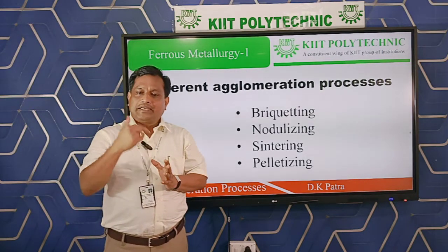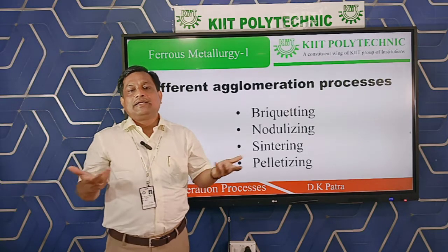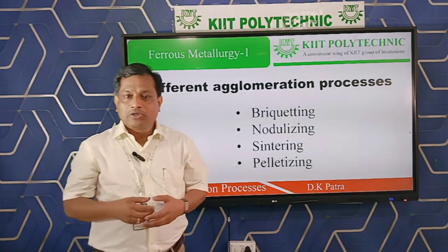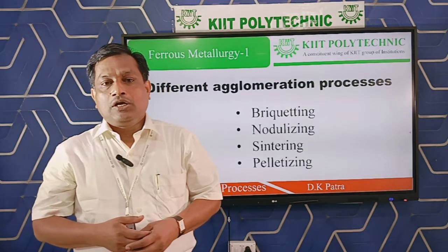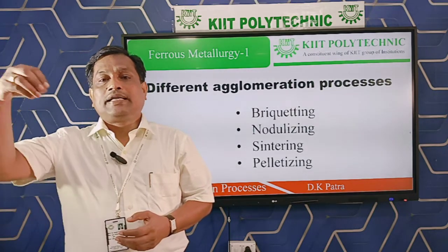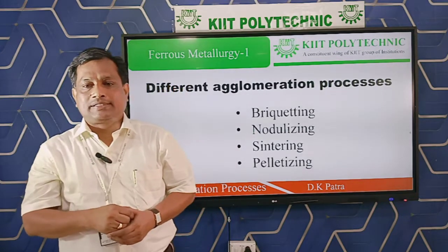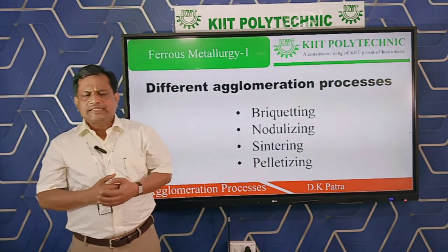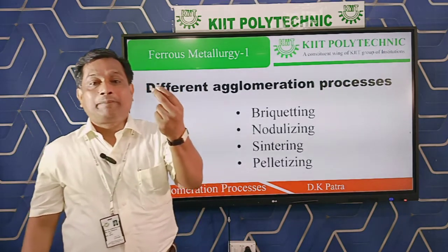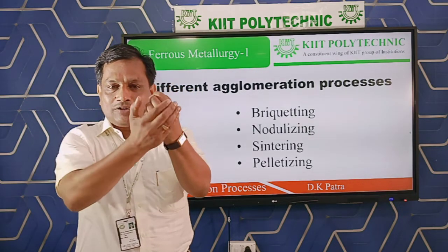Rate of production means that if the carbon monoxide reacts fast with the iron oxide, definitely the rate of reaction will be better and the production rate will be better. So we can increase the production rate. Here they thought: if we put the iron ore directly from the mines into the furnace after breaking it into small particles, what will happen? This reaction rate is a little slow. Why? Because this iron ore is compact and dense. The carbon monoxide is only reacting on the surface.